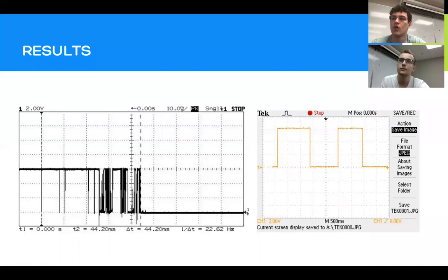And so also shown are our before and after graphs. These are the measurements of the emergency cutoff switch. The first graph shows what the signal looks like without the debouncing circuit implemented, and the second graph shows the signal after implementation. And so notice the large number of rapid bounces on the first graph when the switch is only flipped once, but on the second graph, the switch is turned on and off twice with no sign of bouncing at all.